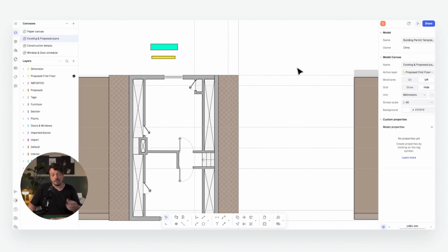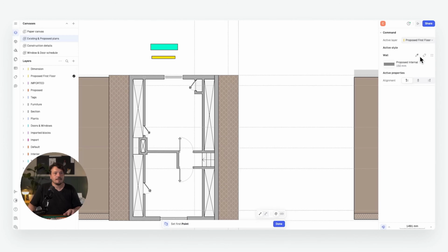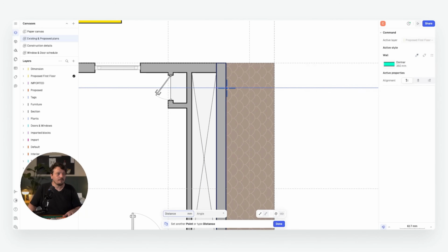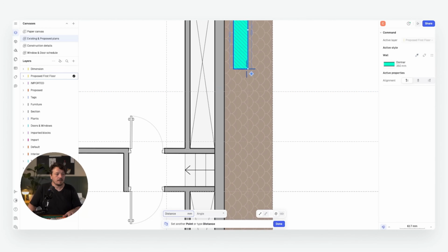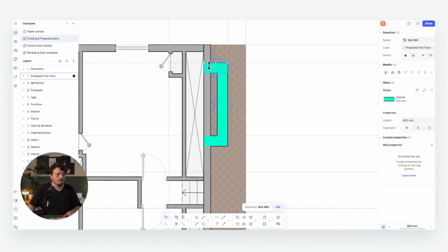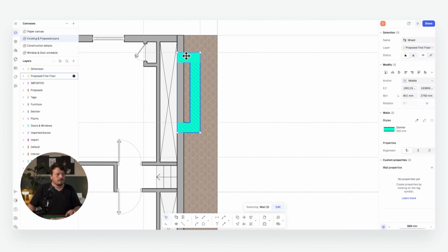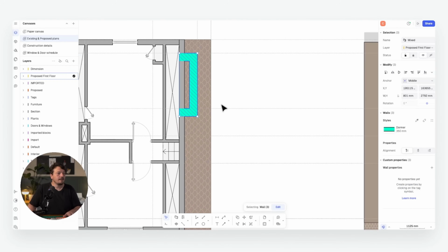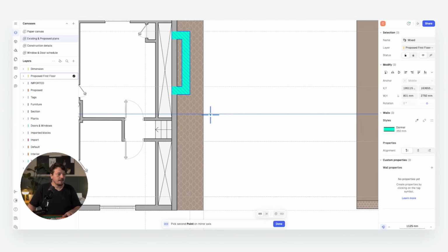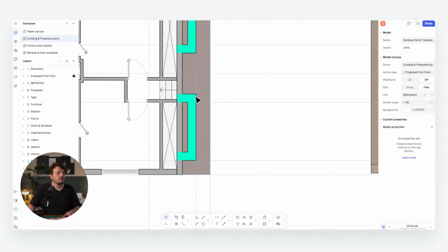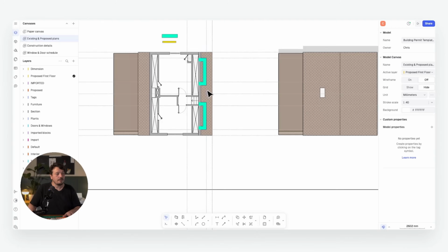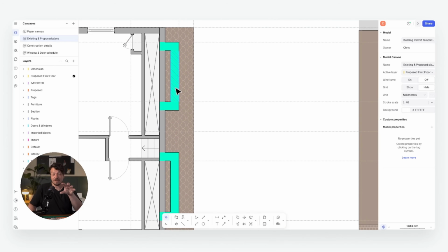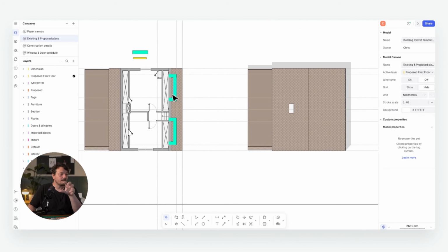And then when we start drawing our walls, obviously we can use our picker style, we'll pick that one, and then we can start drawing from there. So I can then just follow the guidelines that I've created. So that's our dormer wall line, and we can obviously then again mirror, and we can see they're both 600mm off of the edge, and they're sitting centrally within that elevation.